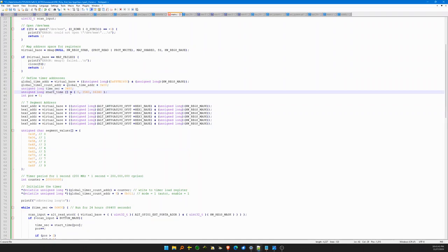And then I have also put 3 additional start times: from 0 seconds, around 59 minutes, and all the way down to 24 hours, 59 minutes. This is just to show when I'm prototyping and displaying it on the 7-segment display that from 0 it goes up by a minute, and when we reach 59 minutes and go up by a minute, it wraps up to an hour, and when it reaches 24 hours, it resets back to 0 seconds.